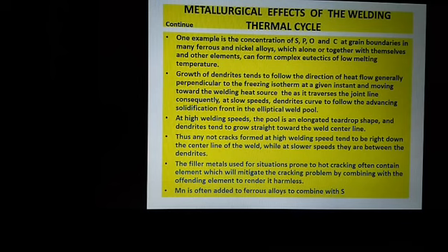Growth of dendrites tends to follow the direction of heat flow, generally perpendicular to the freezing isotherm at a given instant and moving toward the welding heat source. As the heat source traverses the joint line at slow speed, dendrites curve to follow the advancing solidification front in the elliptical weld pool.